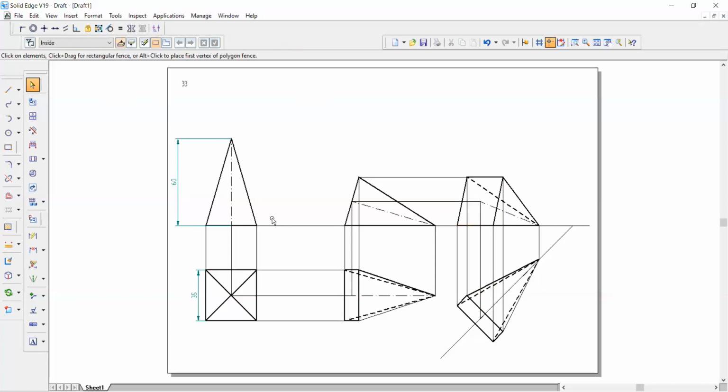So any problem given on slant triangular face, either it may be pentagon or hexagon, you must be able to do this. This is the procedure for your slant triangular face. I hope you are understanding this. Similar problems will be there. I have not shown many of the dimensions here. Just go for angle between.